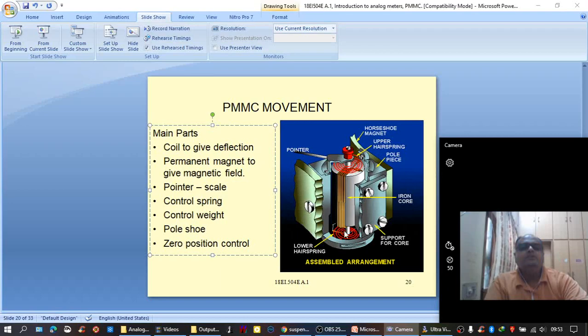The mounting of the movable coil assembly may get disturbed because of the abrupt movement of the pointer from 0 to the specific position multiple times. That means when you are using it multiple times, just in this fashion, that is connected with no power and switched on, all of a sudden the pointer has to make abrupt movement to show the current flowing through that. So in such cases, as I told, the mounting assembly of the movable coil gets disturbed.